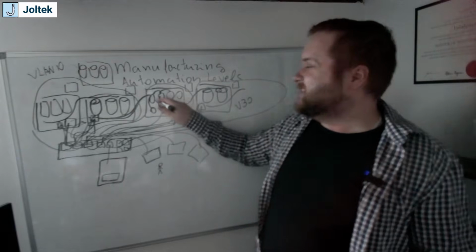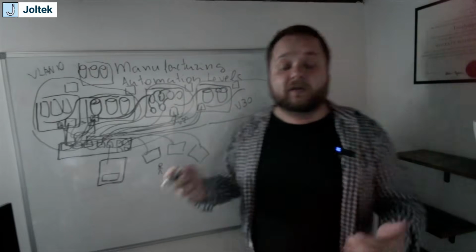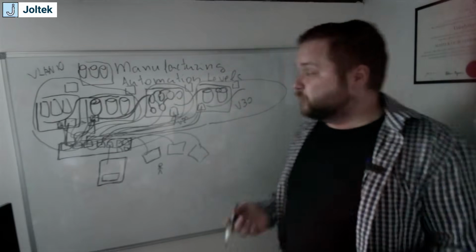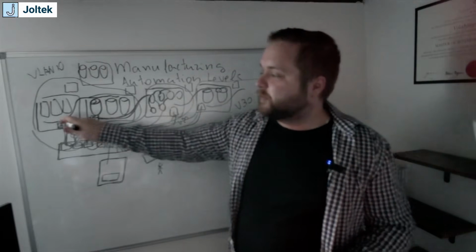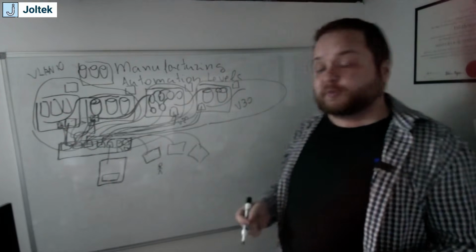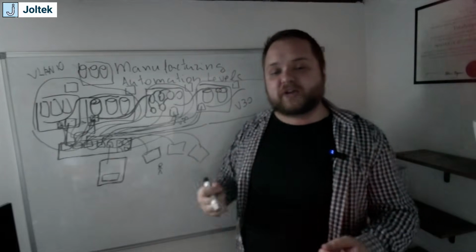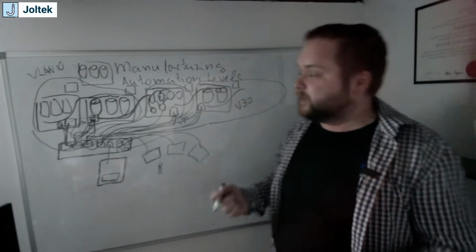We don't want any of the noise that's coming from the other devices, from the vision systems, from the VFDs, from the load cells to go back to, for example, this layer 1 or VLAN 10. And so this is extremely important because as you segment the networks, it also allows you to reuse duplicate IP addresses.